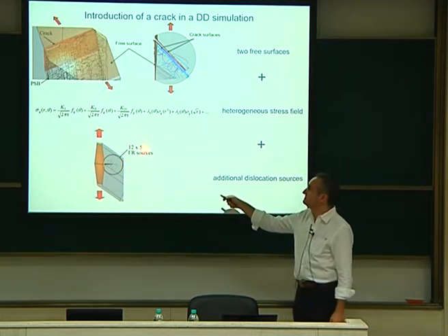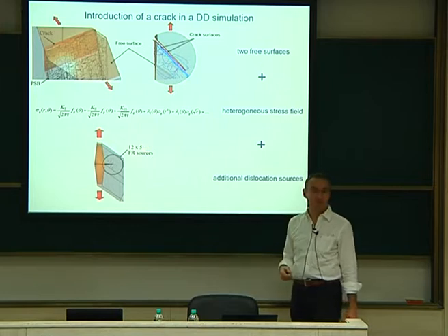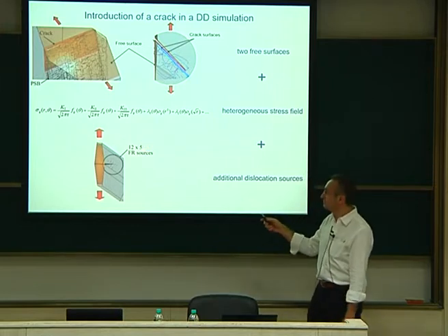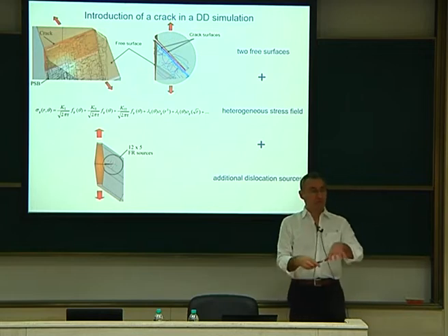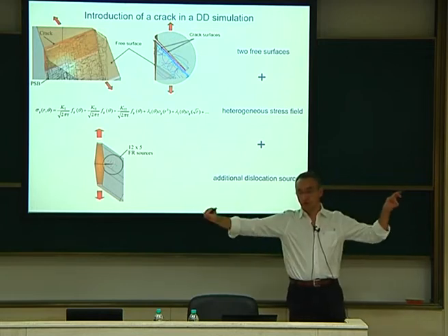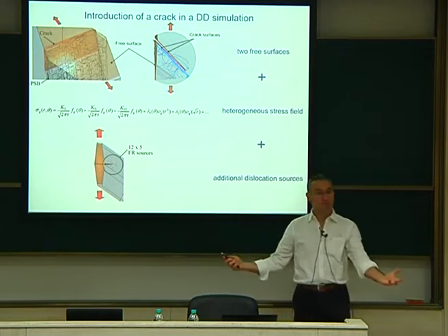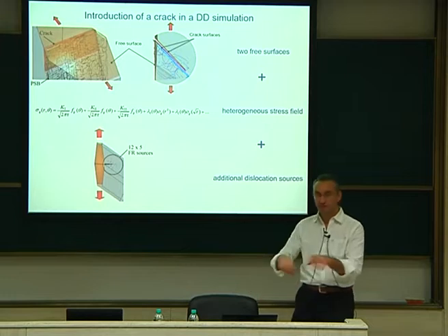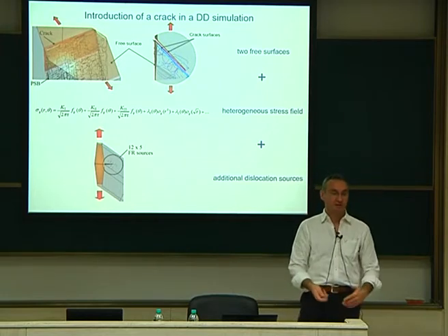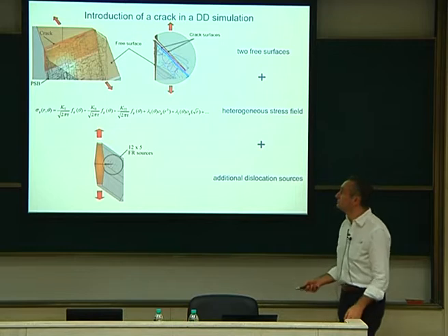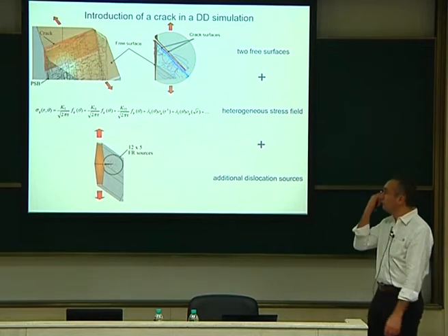So we put five dislocations per slip system, so 60 new dislocation sources ahead of the crack. So somewhere here, there, we put many dislocation sources all along the crack. And we let them move. If they want to accommodate plasticity, then they will do Frank-Read mechanism, cross-slip, whatever. They will accommodate what you apply. As we saw previously, they always do what you apply.